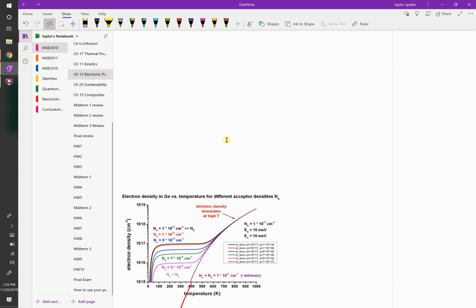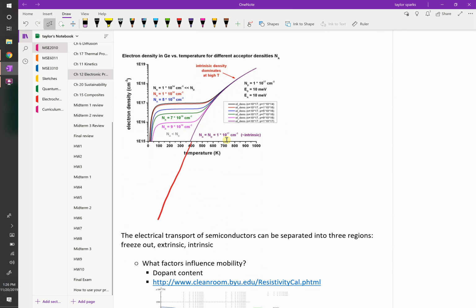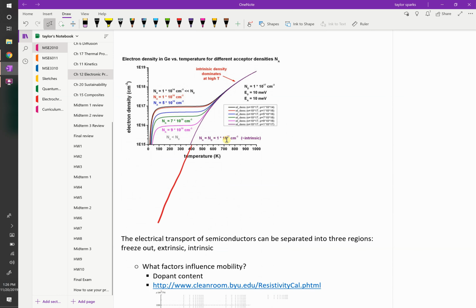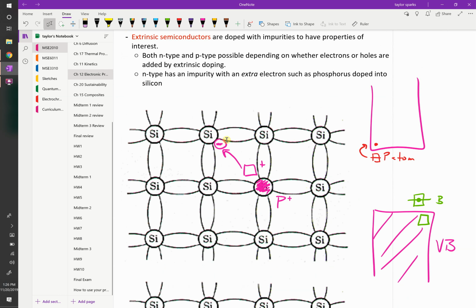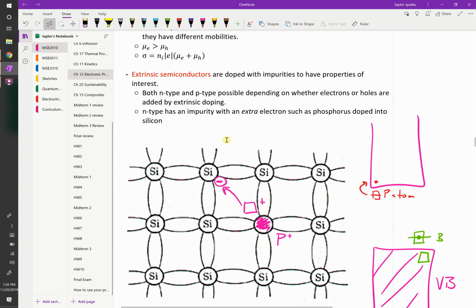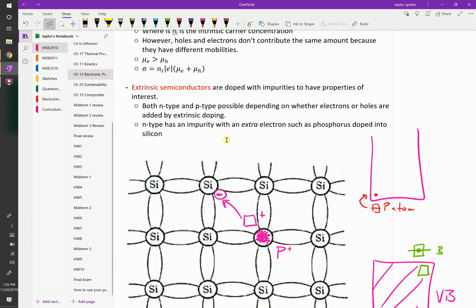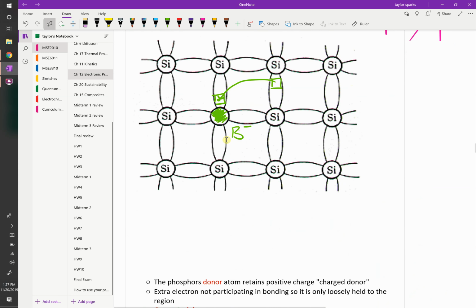This is a pretty cool, yeah, question? Yeah, so when you're looking at phosphorus and it has that empty site, is it easier for an electron from a silicon to fill the phosphorus site or just to jump the whole gap? Oh, technically it would be easier for it to fill the phosphorus site and become ionized, and thereby putting a hole in this band. Yeah, that can happen. But it's still, think of what the energy cost is. It's still big. It's a pretty big jump to go from here to here. And there's a relatively small number of those. But yeah, you're right. Other questions I can answer?